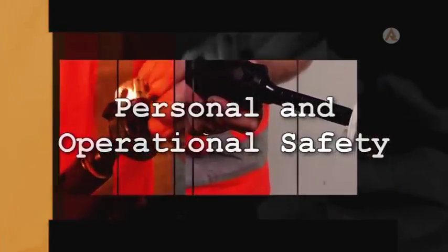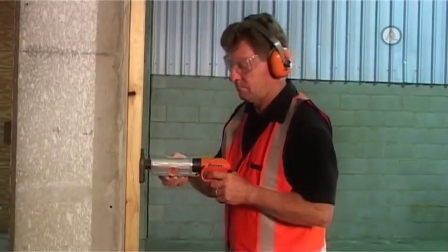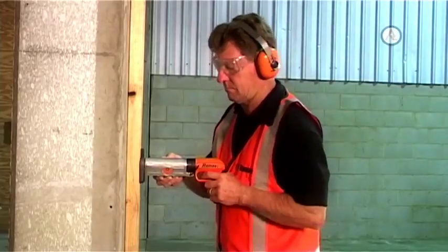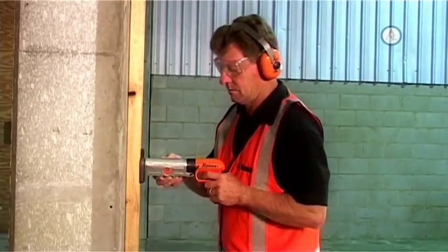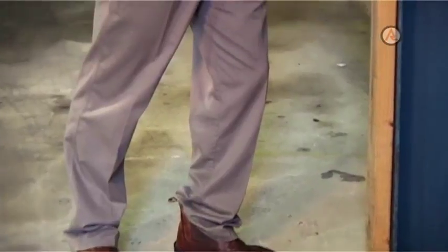When working with powder-actuated fastening tools, eye protection is essential. Safety glasses with side shields must be worn. Earmuffs or plugs must be worn. Safety boots are also required.